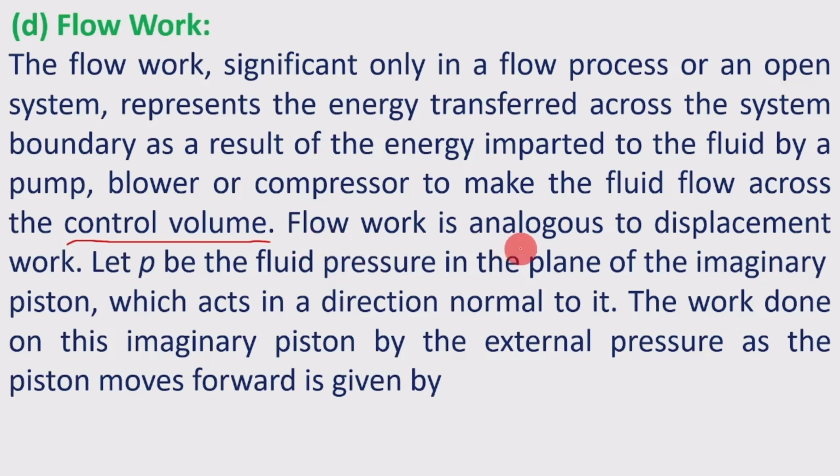And this flow work is analogous to the displacement work, the PdV work. Similar to it is there. For that, let P be the fluid pressure in the plane of the imaginary piston. Okay, that imaginary piston we are going to consider. We'll take in the next slide what that imaginary piston is, which acts in a direction normal to it. The work done on this imaginary piston by the external pressure as the piston moves forward is given by dW equal to PdV, that is the equivalent of the PdV work.